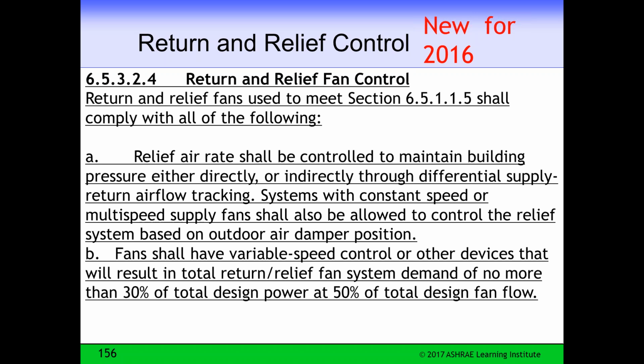So all we're doing is requiring supply-return airflow tracking, because that minimizes the energy used in a system that has both a supply and a return/relief fan. So that's the requirement, how we want that controlled, and we would let you control based on outdoor damper positions for multiple speed fans that aren't required to have VFDs.